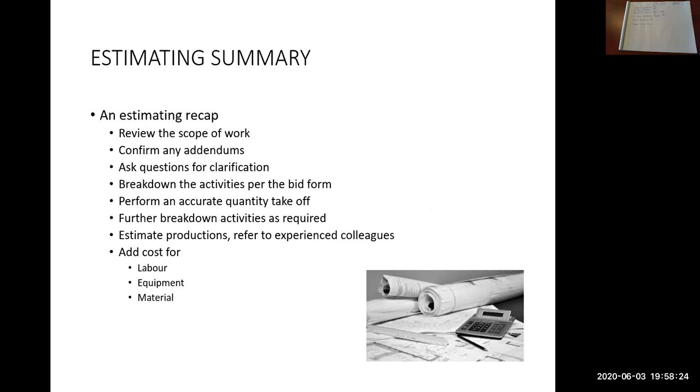You've got layout, you've got trenching, so you come up with volumes. You've got your placing of your bedding and compacting. You've got time for your crew to set the pipe. Then you place the rest of your backfill. And then you do whatever's needed on the surface of the trench. So all of those things can be sub items in your tender item. So maybe you've got 5 sub items inside that one bid item.